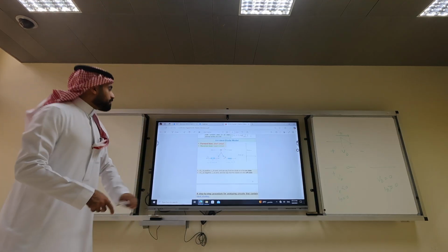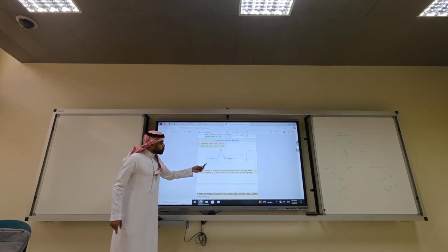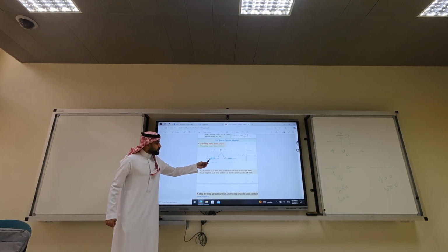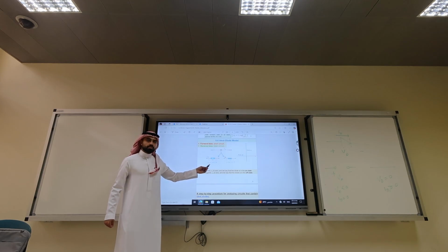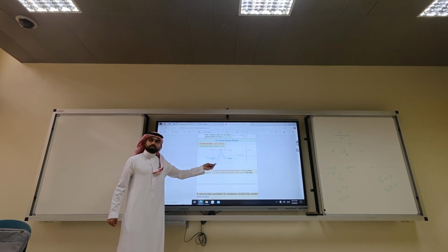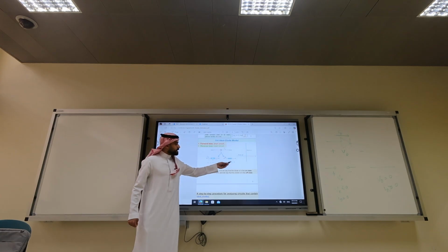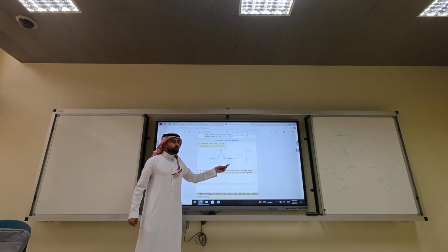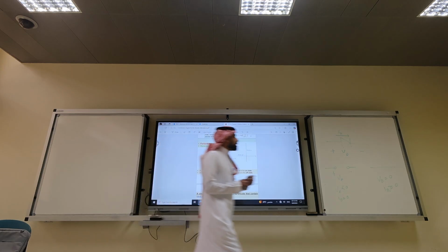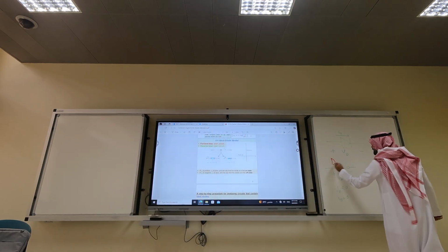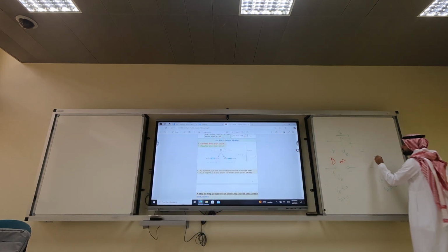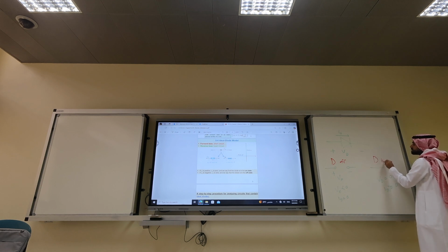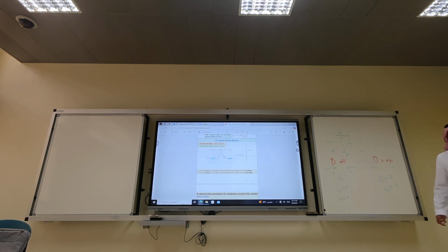What did we say about the first state? Two conditions. VD should be less than 0 and the current should be 0. Or VD should be 0 and the current should be larger than 0. So this state we call the diode is off, here we call the diode is on. Get it?